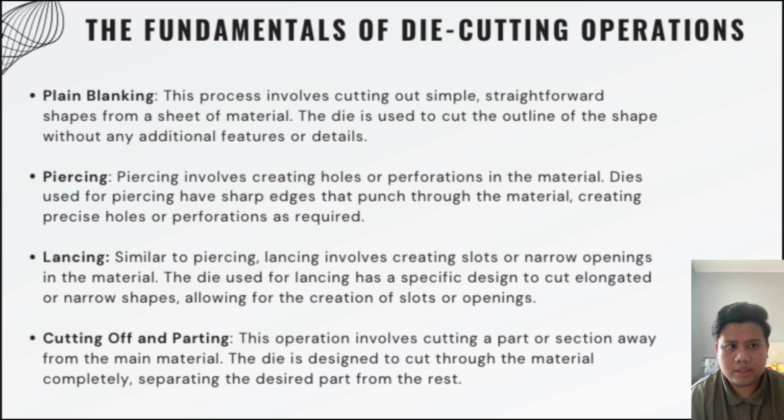allowing for the creation of slot or opening. Cutting off and parting. This operation involves cutting a part section away from the main material. The die is designed to cut through material completely, separating the desired part from the rest.